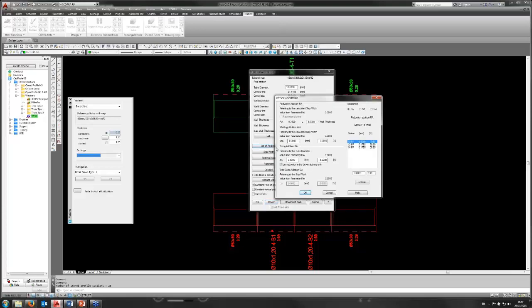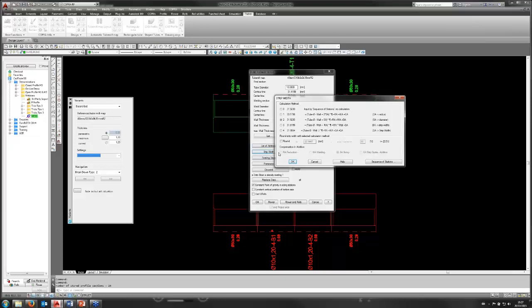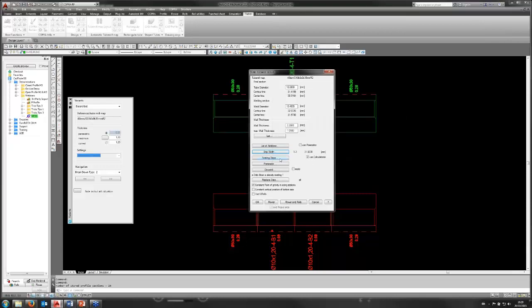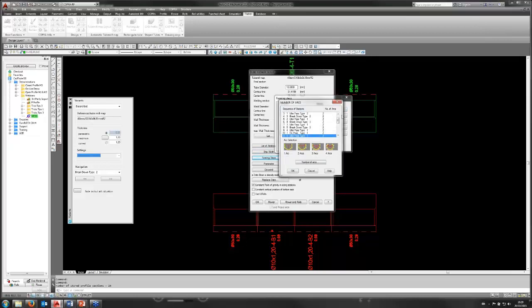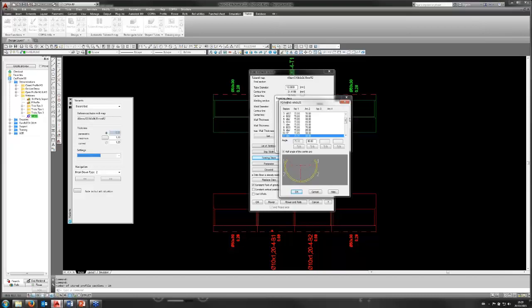We have a list of additions here for our fin passes, our weld addition, sizing additions, and so on. Multiple opportunities here for our strip width calculation, and of course if we have a strip width we need to maintain, we can also use that one. And we look at our forming steps, you can see here we have strategies for different arcs. So if we imagine without the software we would have to construct all of this information manually, even in CAD. Our angles here for forming as well, so we can very quickly and easily define the forming angles we intend to use.